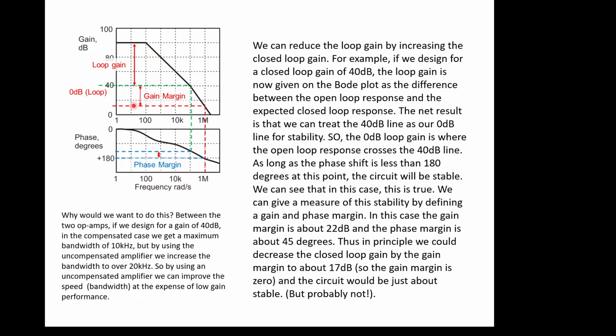Likewise, we can actually measure a gain margin, which is saying at what point does it become 180 degrees in terms of gain, and what gain are we operating at, which is the green line. We take the difference between it, and that's the gain margin. That's how much spare gain we've got to play with in our system before it becomes unstable. And you want to have a bit of gain margin because not all amplifiers are the same, and these poles can move around a little bit as well. Right, so that's how we can improve the stability of our system a little bit.